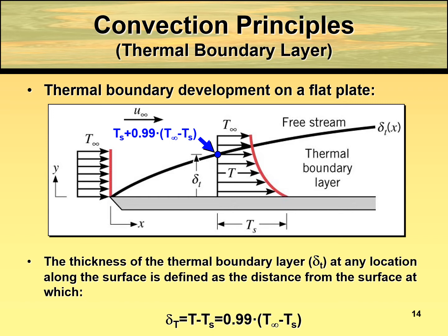The no slip condition for the velocity boundary layer starts at zero, but for the thermal boundary layer it starts at Ts, where you have a free stream temperature T infinity and the surface temperature of Ts. Then you have a temperature profile for the thermal boundary layer that is in a reducing condition.